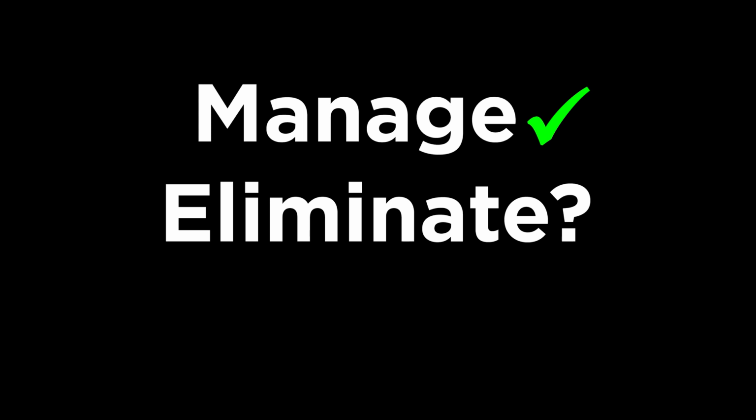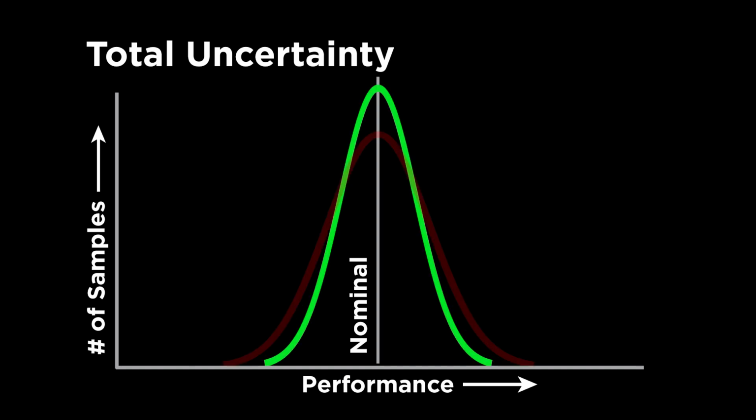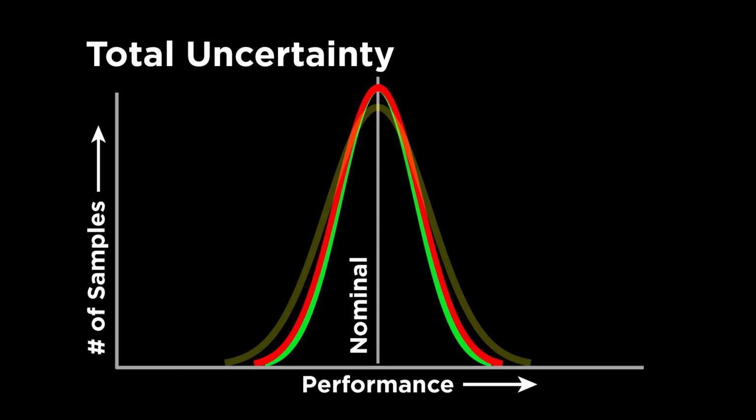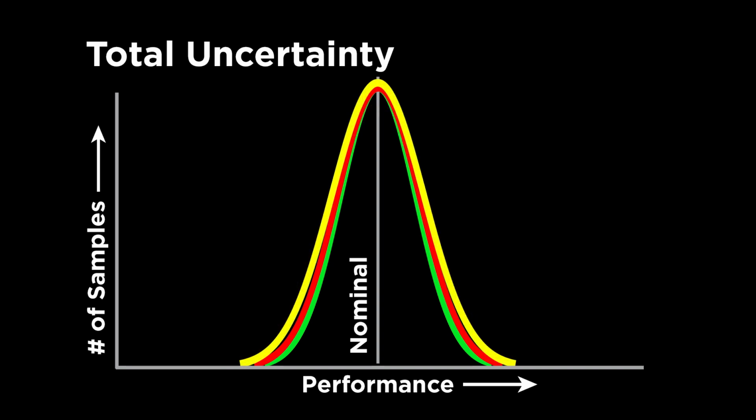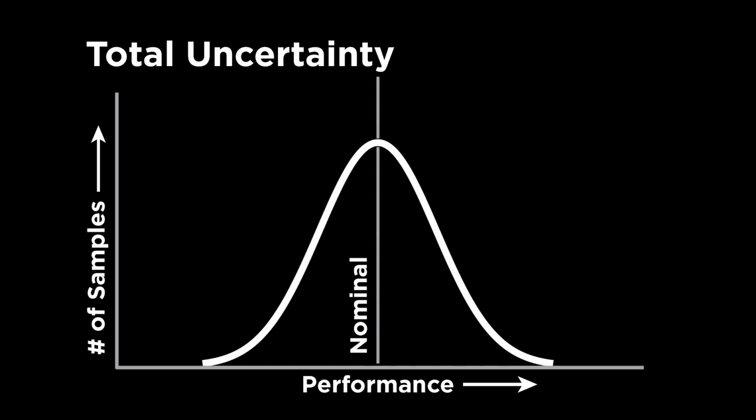Manage, yes. Eliminate, no. The impact of these uncertainties can be minimized by using more accurate measurement systems, relying on a single lab for data generation, decreasing manufacturing tolerances, selecting a broader, more precise range of test points for systemic validation testing, and testing at rated conditions. By focusing on these 5 steps, it is possible to manage the uncertainties but not to eliminate them.